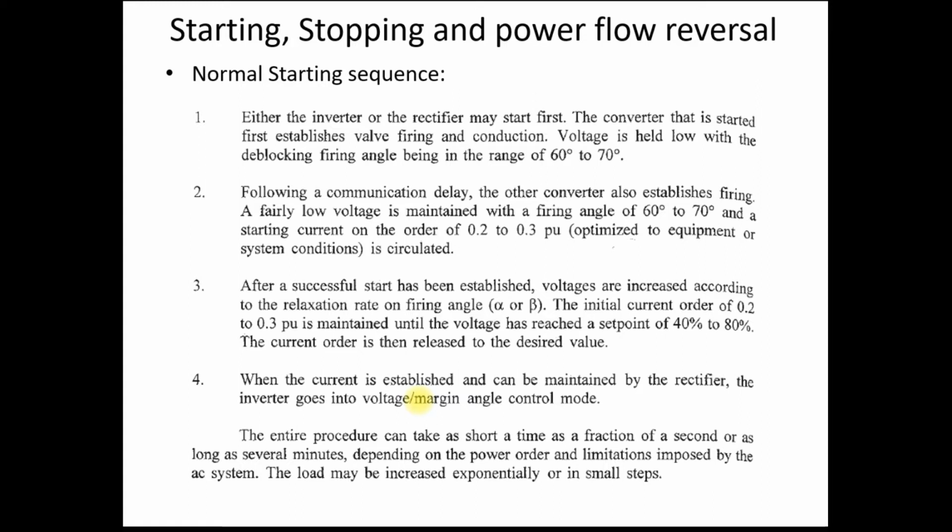Does this entire procedure take a fraction of a second or as long as several minutes? That depends upon the power order and the limitations imposed by the AC system. So depending upon the requirements, the starting of the HVDC system takes several seconds to a few minutes.